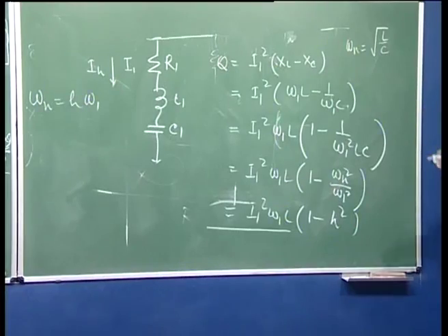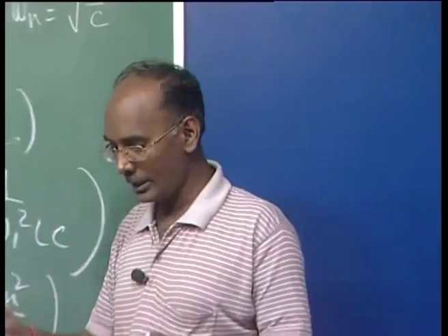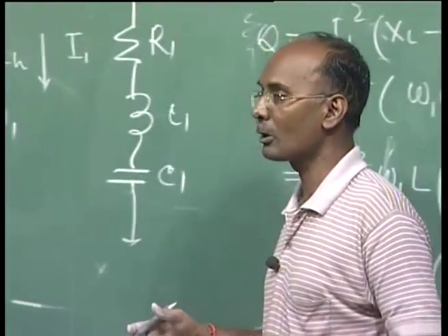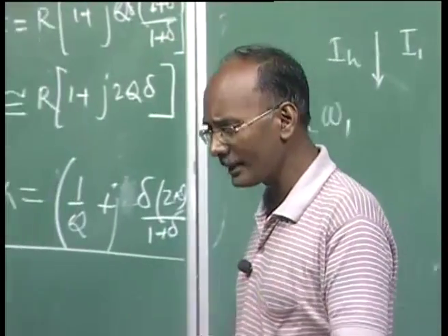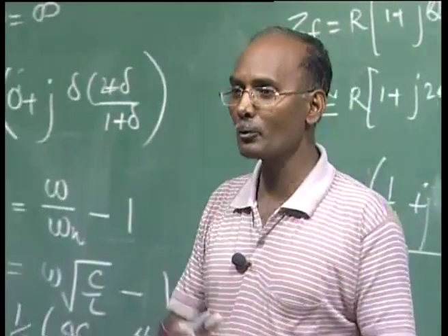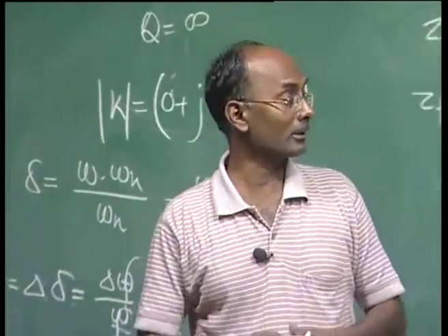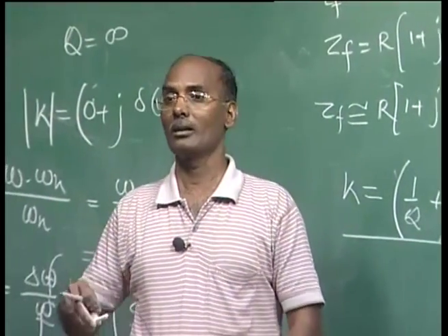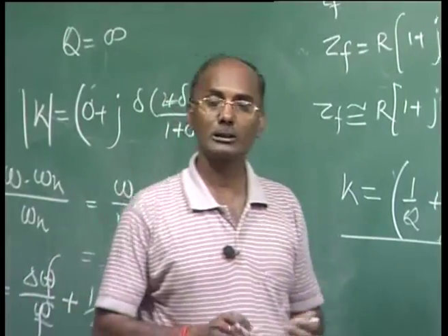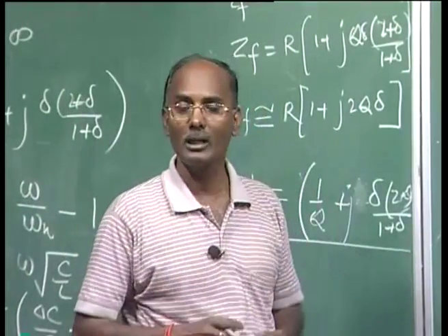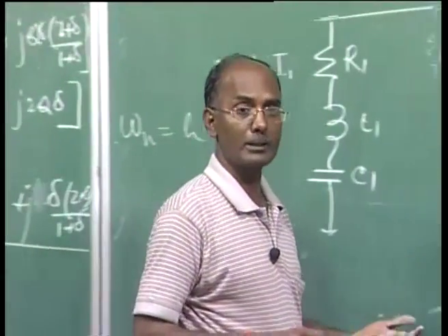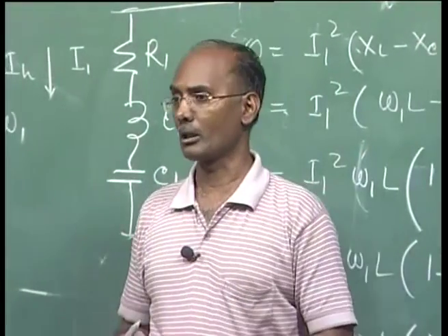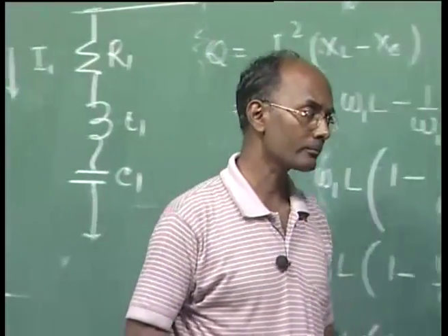So that's why we go only for the lower order harmonics. If we are operating with 6 pulse converters, then we go for 5th, 7th, 11th and 13th. If you are going for 12 pulse converters, then we use tuned filters for 11 and 13, and the remaining we can either pass to the system, or sometimes use a band pass filter nearby, so that it does not go to the AC system.